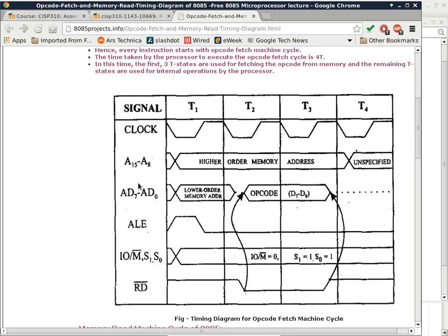For those of you who don't know what I'm talking about, the number of layers in the circuit board, what does the circuit board look like to you? When you go to Fry's, you go by the motherboard, what does it look like? Well, it looks like a piece of plastic, right? If you look at a circuit board without components, it almost looks just like a piece of plastic, except it's not made out of plastic. It's made out of what we usually refer to as FR4 material. FR4 is a kind of fiberglass. It's resin reinforced, so it's pretty hard material.